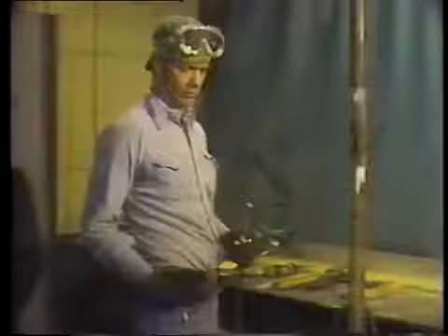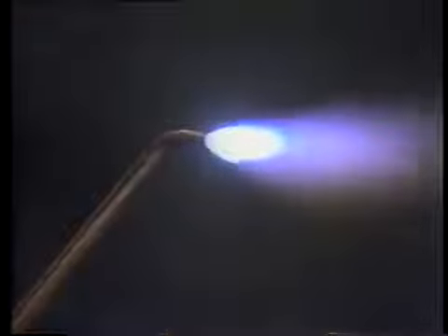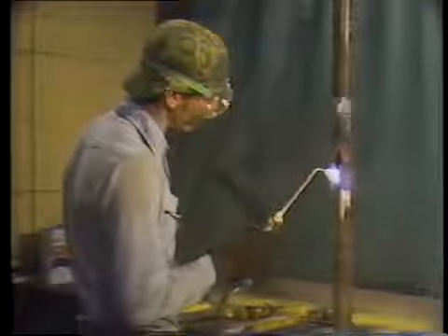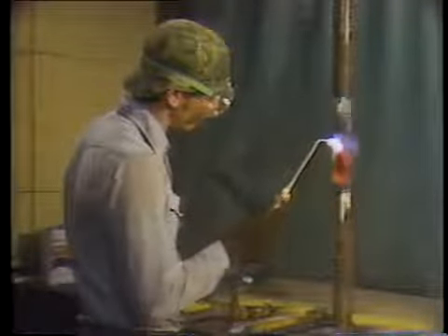First, use the gas torch to heat the metal around the opening. Adjust the torch until it has a broad flame. Move the flame over the tube to heat it evenly. The tube should be heated until it's cherry red. If you hold the torch too close to the tube, it will get too hot. The tube should be hot enough to bend, not hot enough to melt.